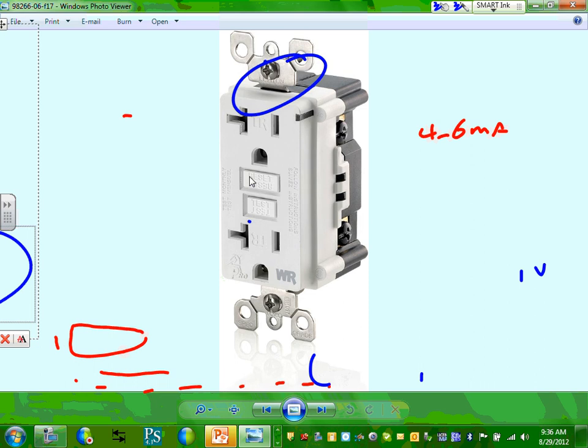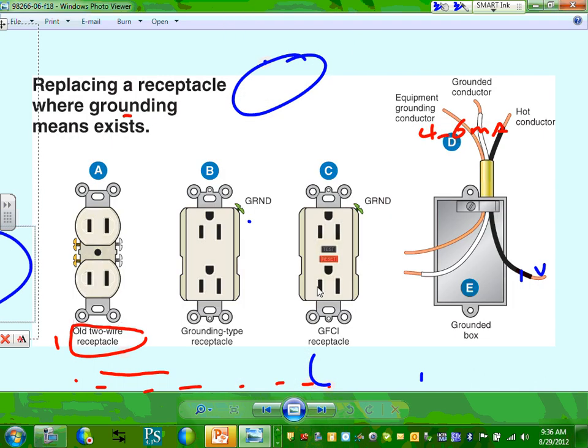So if you're outside, you have to have a GFCI receptacle first, or GFCI protected. You have to have tamper resistance and weather resistance, right? And an in-use cover. Everybody okay with that one? All these requirements, so they have one for you.